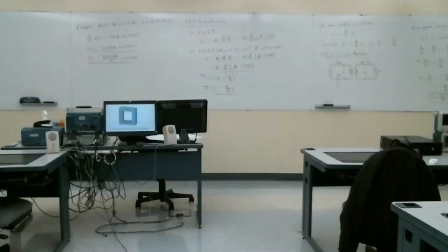Okay. The other thing is, with current directions as shown, the power relationship was I1 V1 is I2 V2. And so I2 over I1 was N1 over N2. Again, this though comes from my power convention. Whereas in our textbook, he's got a minus sign in there because he has I2 going in the other direction.